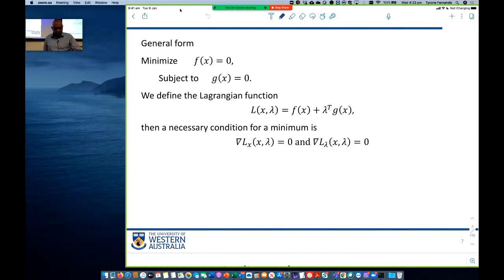We want to minimize f subject to g(x) equal to 0. g(x) equals 0 is the constraint, right? So in this situation, what is f? f is the cost of electricity. And g(x) equal to 0 is the generation minus the load must equal 0.